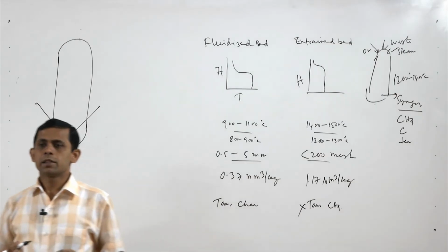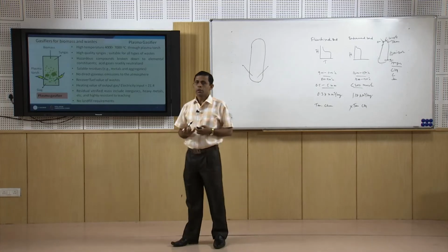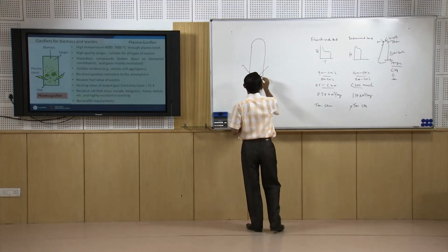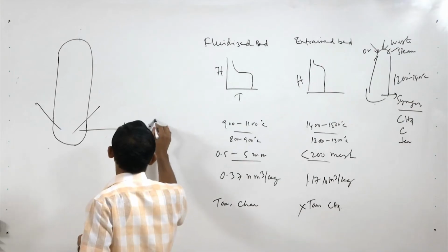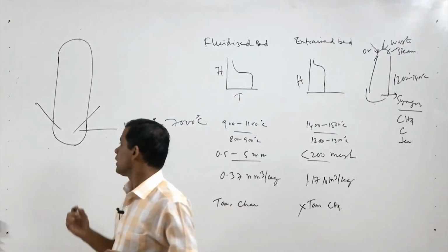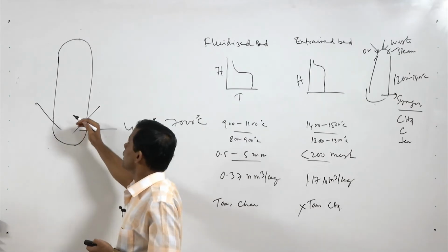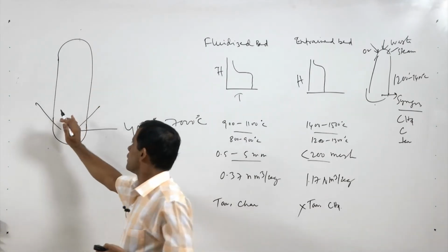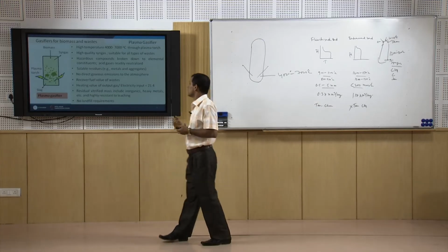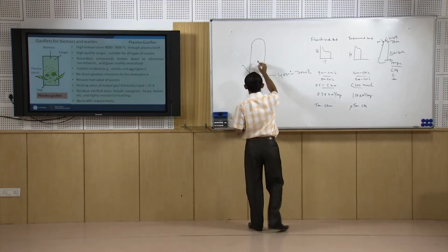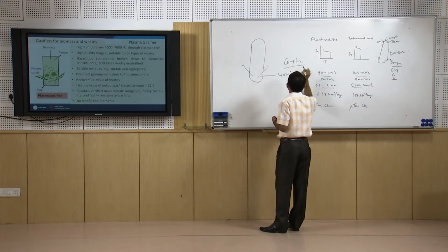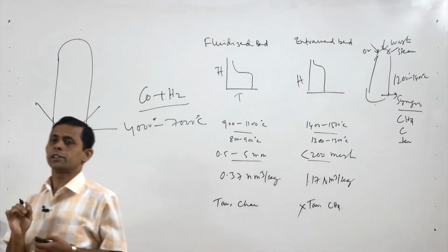The high voltage given across these two electrodes produces a plasma torch, and that creates a very high temperature here, say 4000 degree centigrade to 7000 degree centigrade. This high temperature helps the conversion of the solid waste and biomass present in it to gaseous products, and when carbonaceous feedstocks come inside, a CO and H2 rich gas is obtained under certain conditions.